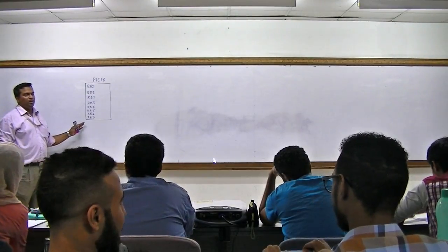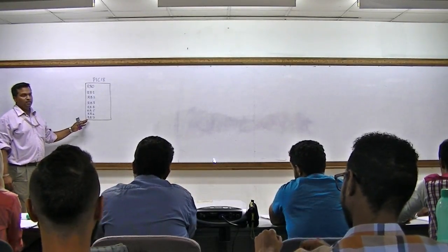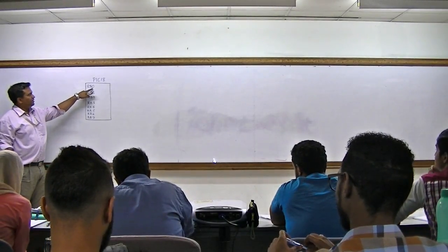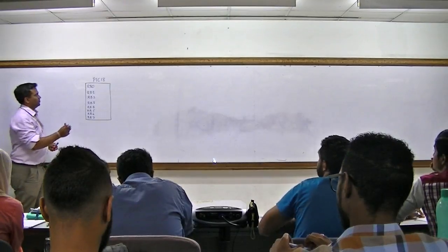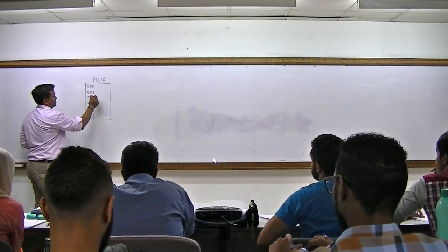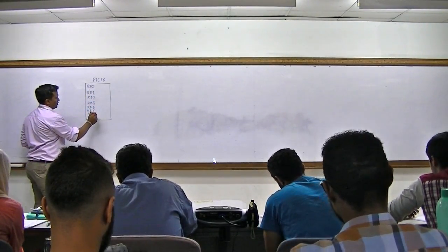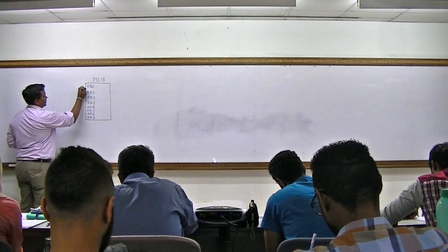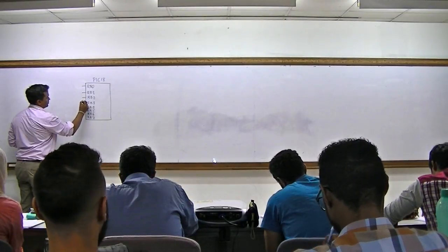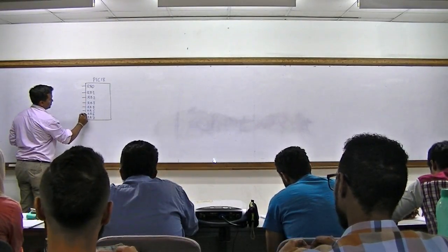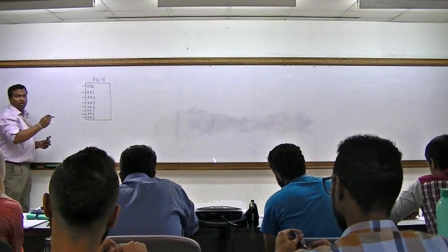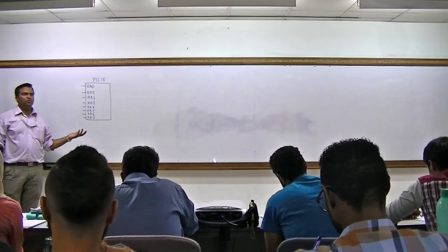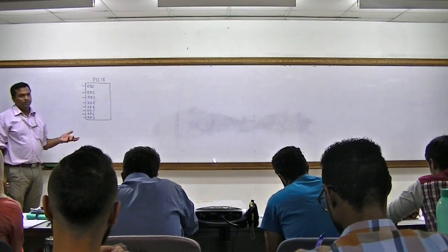here for this example, I'm focusing on port B. So RB is referring to port B, and this one indicates the pin number. Now, as I mentioned, all these pins, we have the input-output pins. Now these input-output pins you can configure whether to become input or to become output.